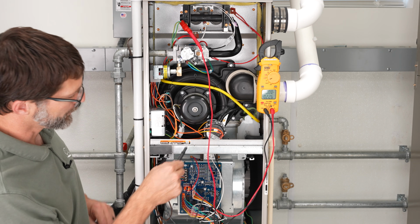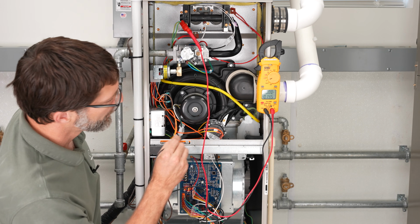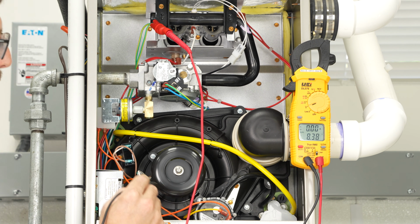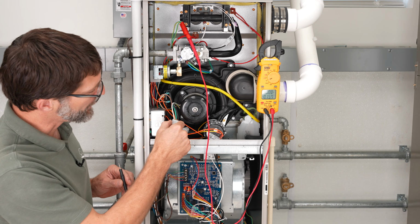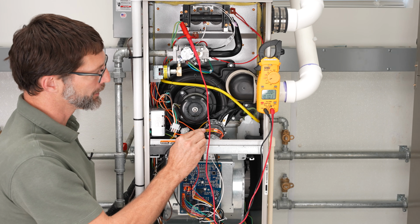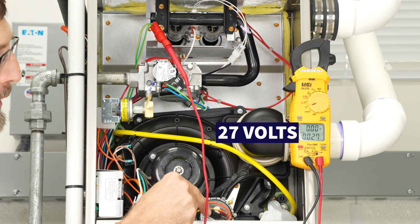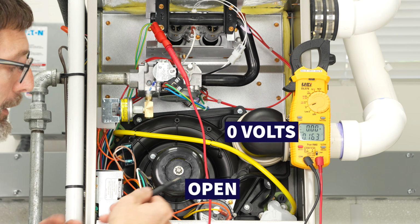So right now, you see, once I remove the jumper from down there, we now have this switch is closed right here, but that's because the inducer motor is running. What we've done now is disconnect our inducer motor, and so what I want to do is show you what it should be measuring. With the inducer motor off, you see we're measuring 27 volts on one side, and on the other side we're measuring 0 because that switch should be open. And it is right now.